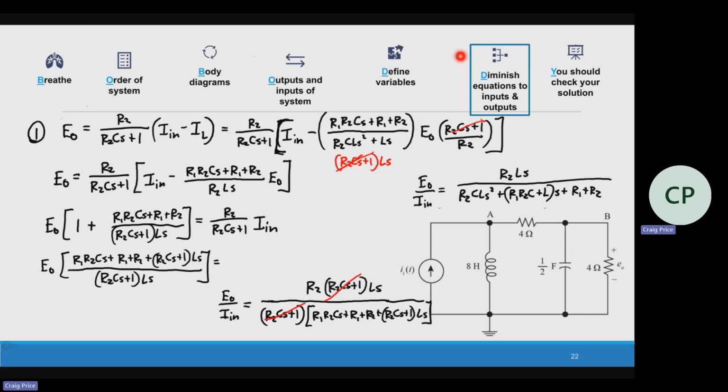And I don't know if the other method, going through KVL, KCL, might have been faster. Again, like I said, it could have been, depending on your skill with this. The real wrench in the system was that R1 right there. It really made it difficult. And there are other ways you could probably look at the problem, depending on your experience with impedance, but we should be able to get to a second order equation.